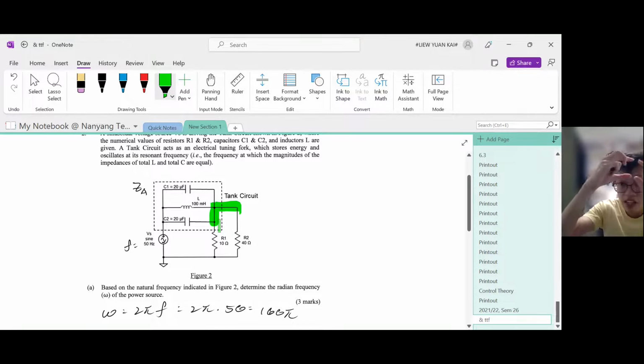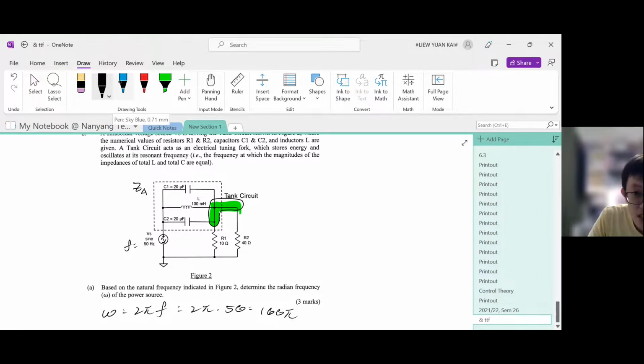This whole green highlighted part, that L-shaped part, is a single node. Why? Just circle it and ask yourself, is there any device? No device, no device. It's one whole node. And this too is just one node. The two ends are connected to the same two nodes, which means they are parallel.